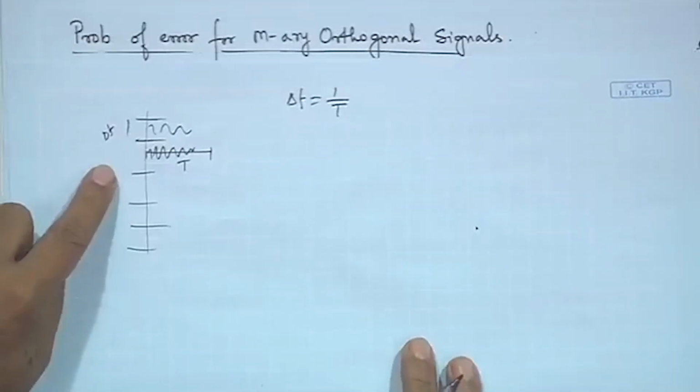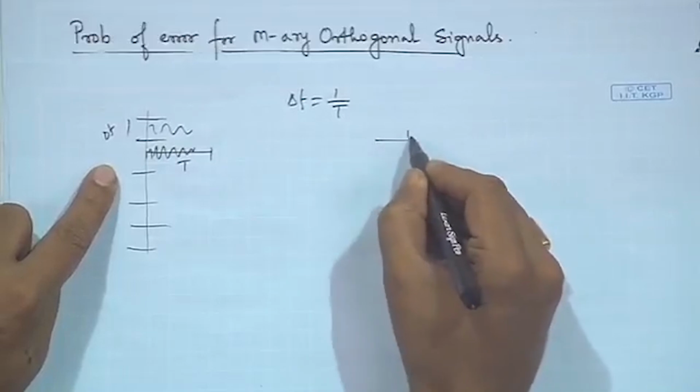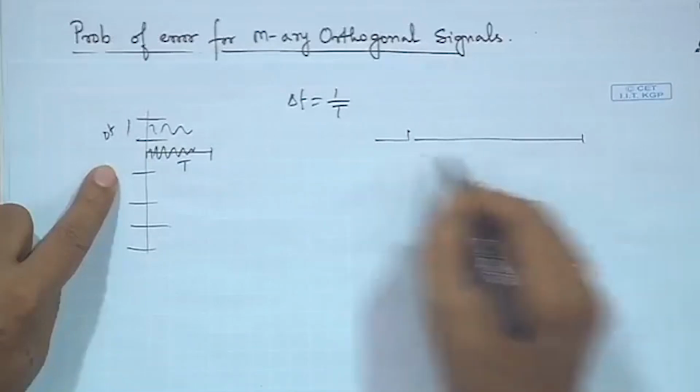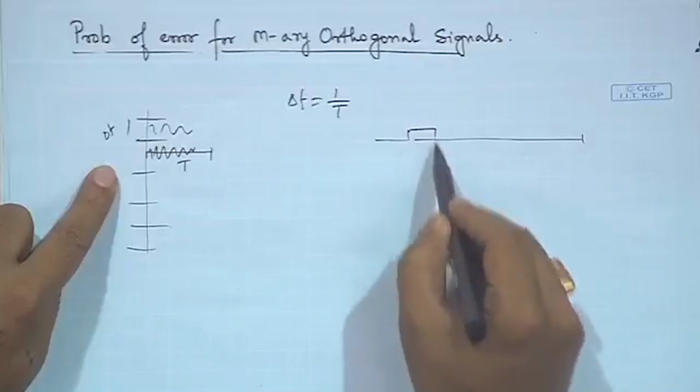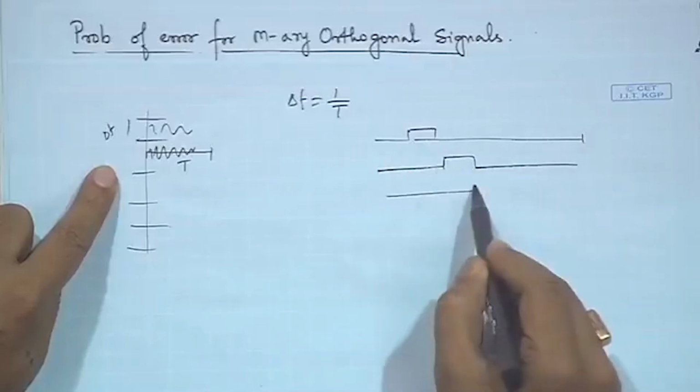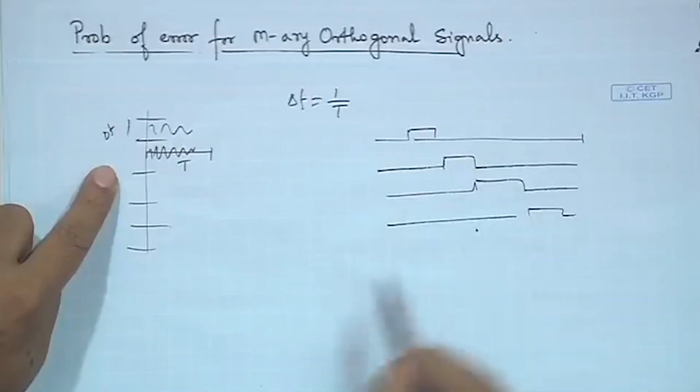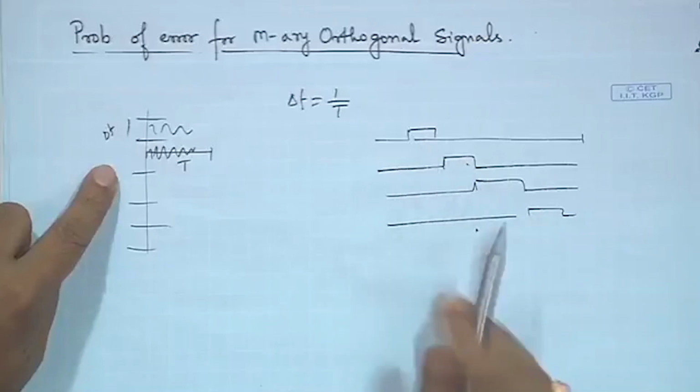And the realization was the correlation of the received signal with a particular one of the signal waveforms, minus the energy of that particular signal. So, effectively what we had was the correlation. Now, if we have the M-ary orthogonal signals, recall this structure, or the situation where there was a long time duration T and one could use orthogonal time slots, and each time slot had the same energy.